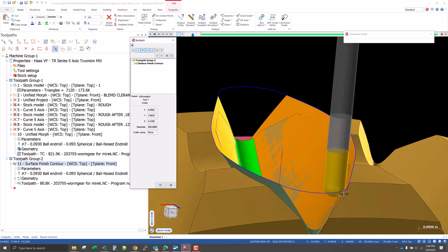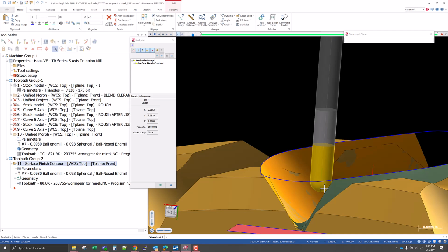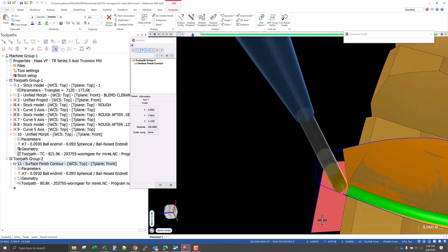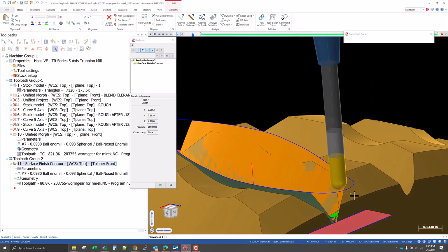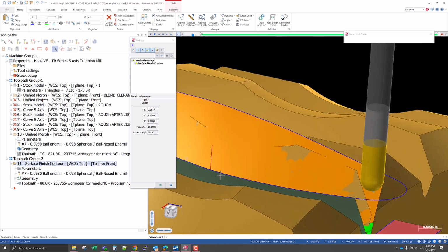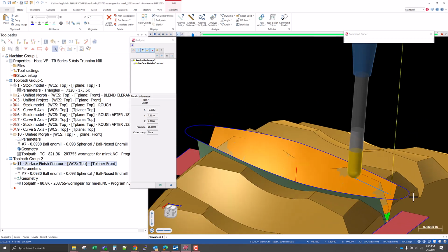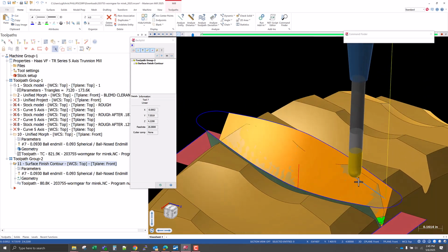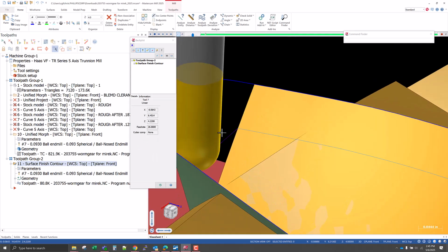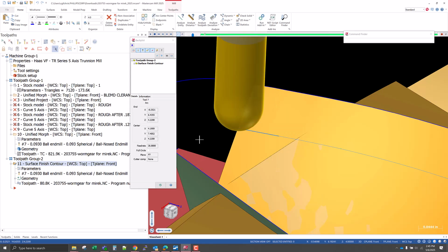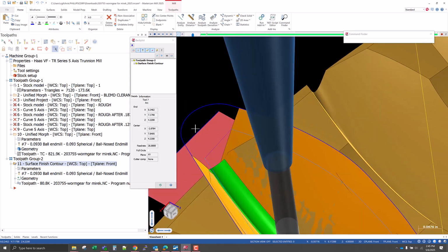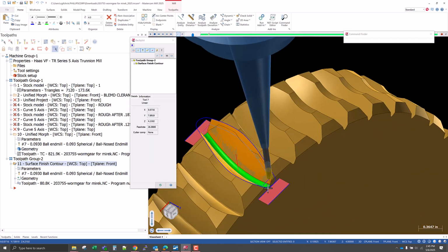Okay, so here we are, plunges down, plunged in at 200 inches a minute. What don't we have there? Well, we don't have any actual material. So we planned it out so we're feeding down off of the part itself. And now as we step in, you can see it actually went to the real feed rate, 26.88. And we're going across there. It should be using that transition motion. So it doesn't necessarily always work.